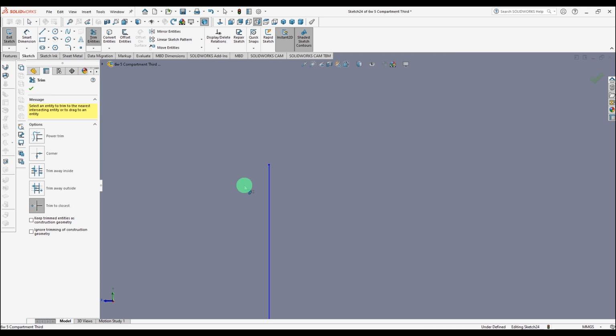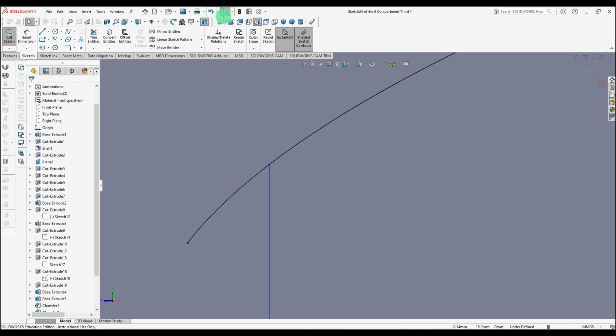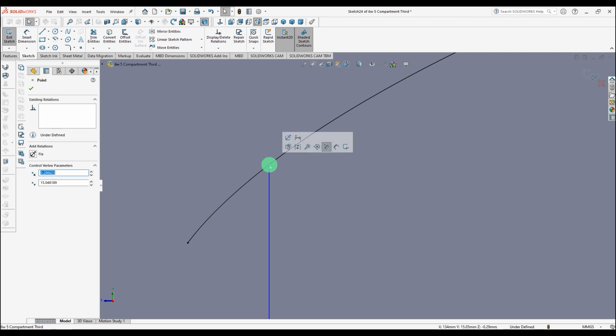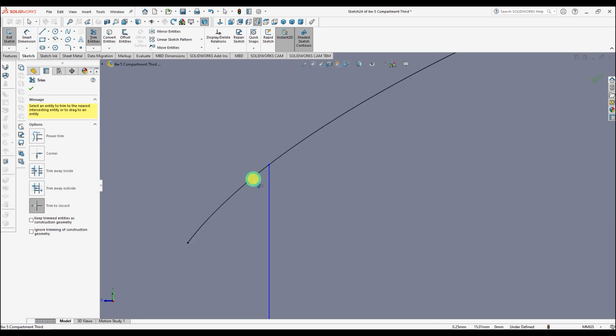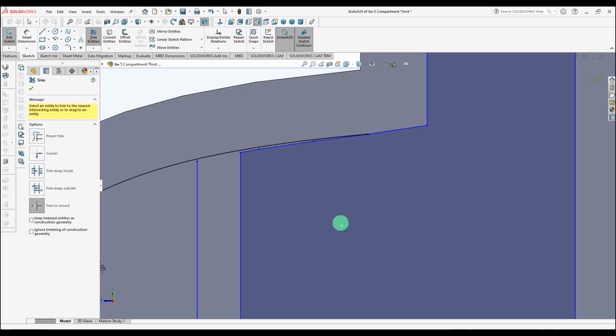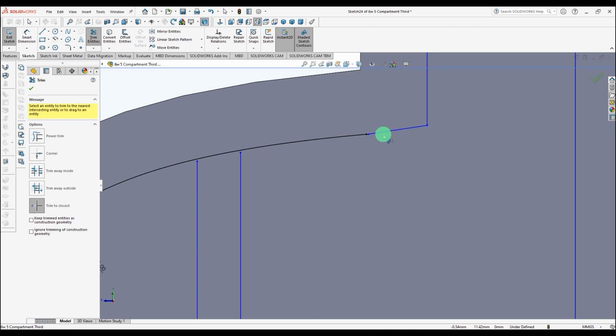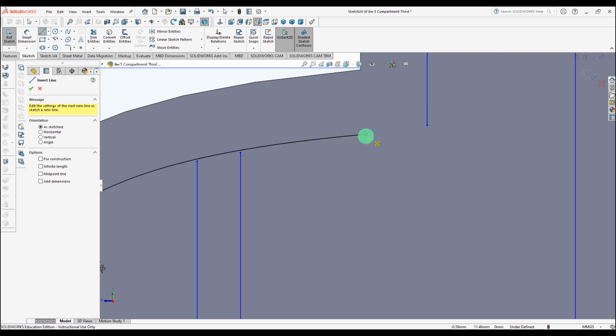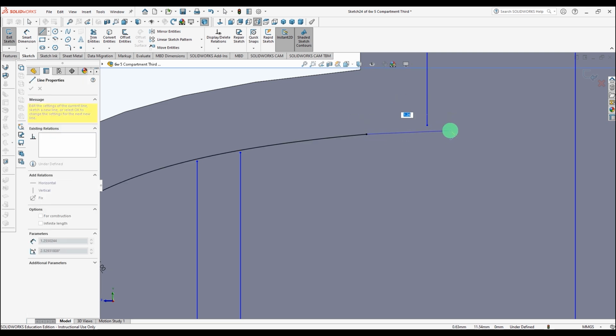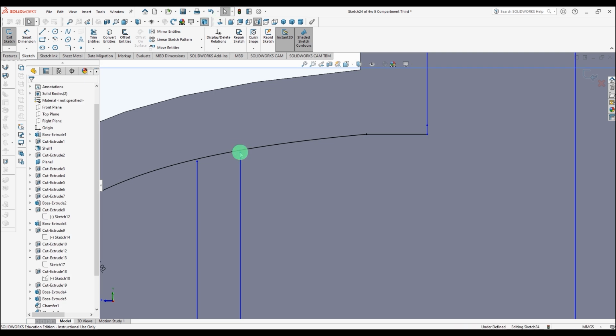And just as before, when I've got the complete profile, it will highlight it in blue. Then I know I'm ready to proceed and the next operation will work. If I try extruding these before the profile is completed, it'll create all sorts of problems and we'll get stuck. And this is often one of the hiccups when you're learning to do this for the first time, you can't work out why stuff isn't working. Well, with 3D modelling it's always a 2D profile that's either extruded or cut away, and if your 2D profile isn't complete then there will be problems.